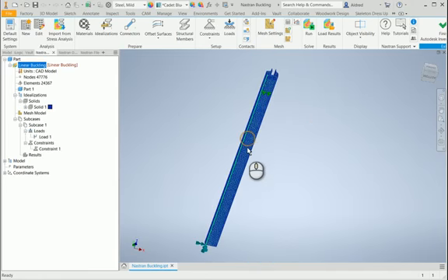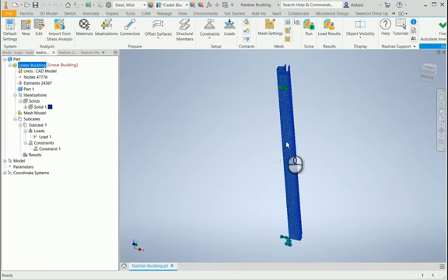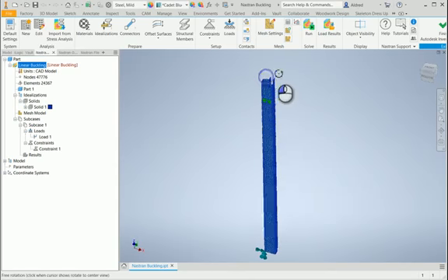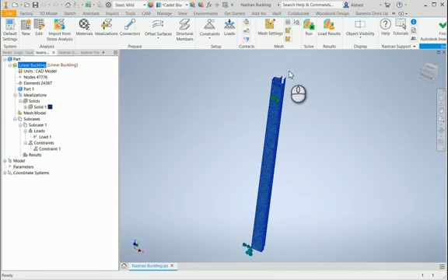That's basically all I need for my simulation to get the critical value for buckling, and then we click on run. Oh, before I do that, my apologies, you need to make sure that you've got the correct material on. So go to the materials.